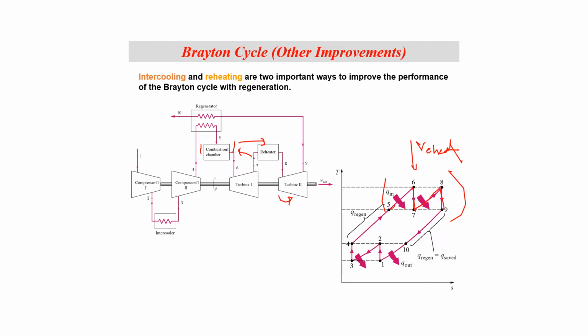So intercooling is a little similar in a way that when we start to compress gas, its temperature starts to rise. But for example, if we just let this gas compress from point 1 to, let's say, here, what happens is we have a lot of input work, and a lot of temperature has risen because of the compression work, and we have not utilized this system to the best efficiency.